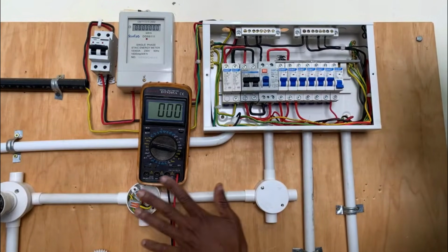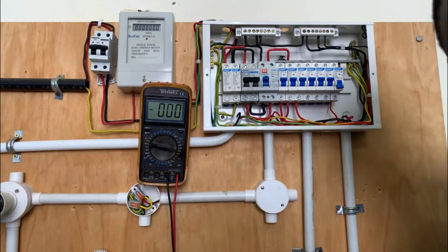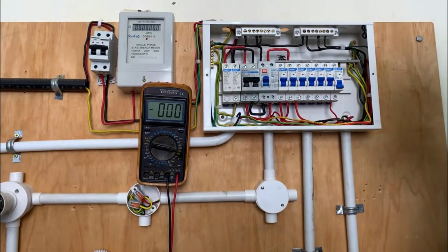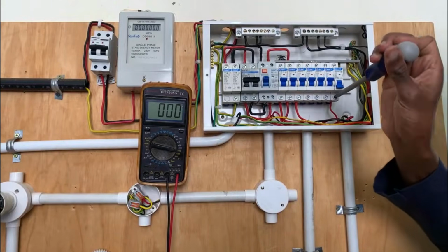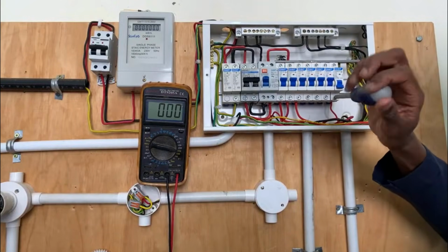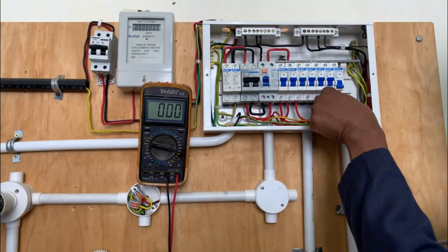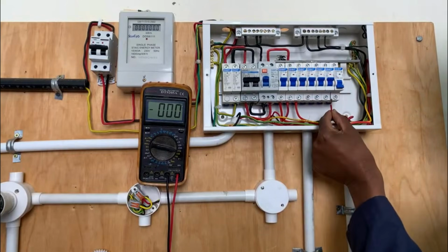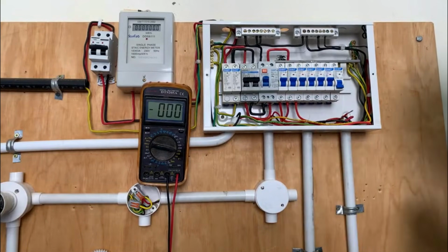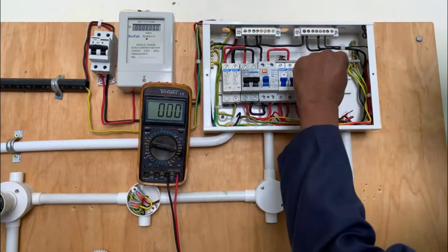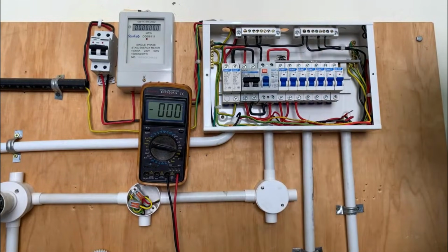They'll say that we have started by isolating the respective lighting points by switching them on. Now, for me, what I will do is to completely isolate the MCB by simply unscrewing that line. So this is the line that is going to that particular circuit. Now, if I switch this MCB on and it sticks, it doesn't trip, it means that it is mechanically sound.